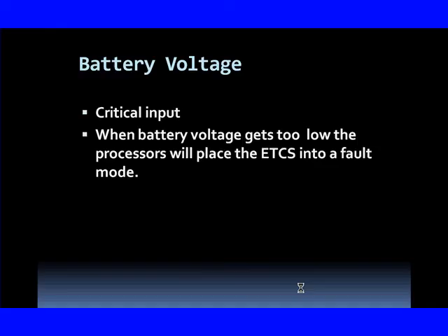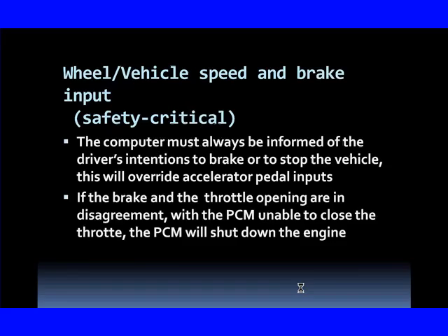But remember this. It could be that this system is doing strange things because the processor has a problem reading battery voltage: a loose connection, a bad terminal. We've seen some outlandish things putting these systems into a default limited performance mode.